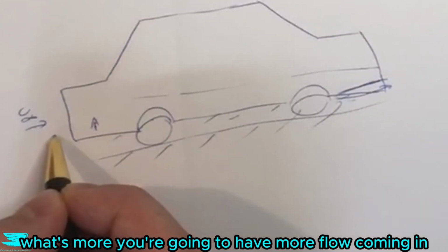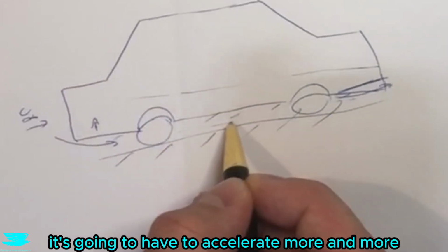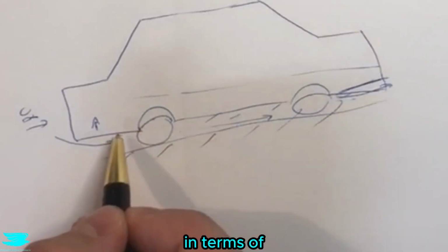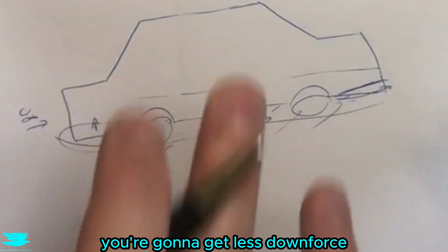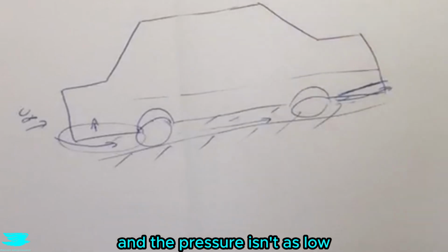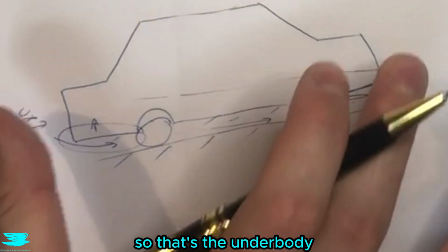What's more, you're going to have more flow coming in, and as you go along, it's going to have to accelerate more and more. So the underbody may not be working the same way in terms of you're going to get less downforce at the front because the flow is not moving as fast and the pressure isn't as low. So that's the underbody.